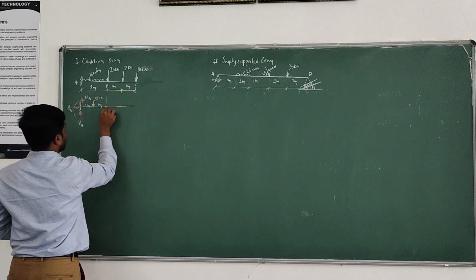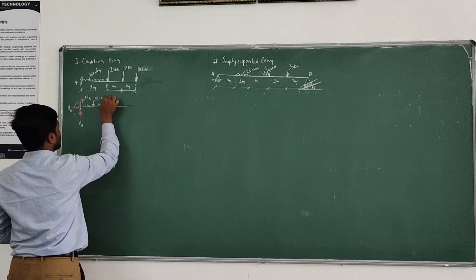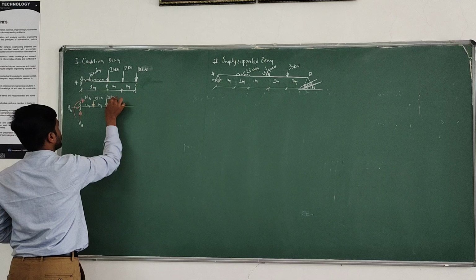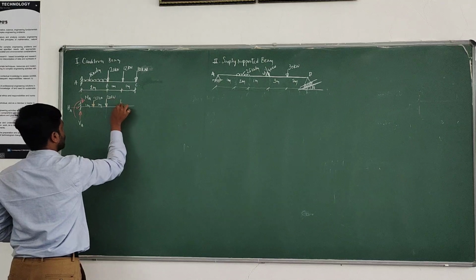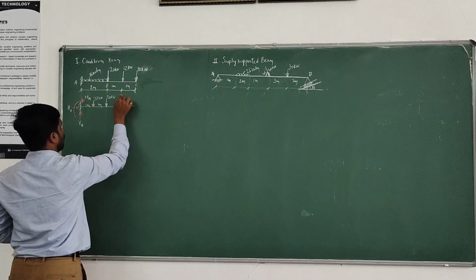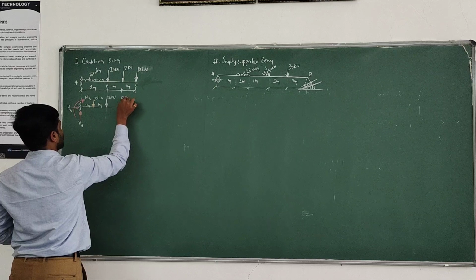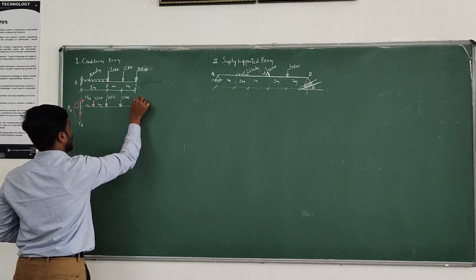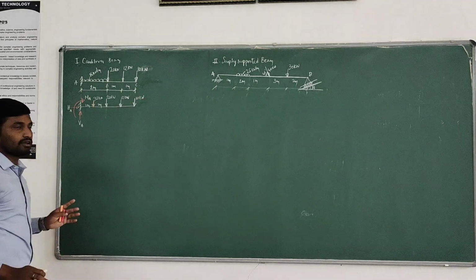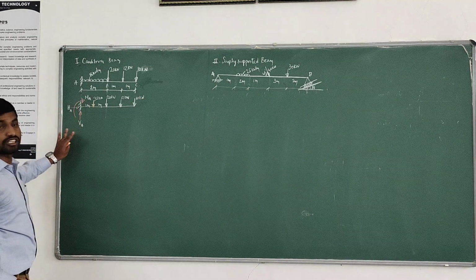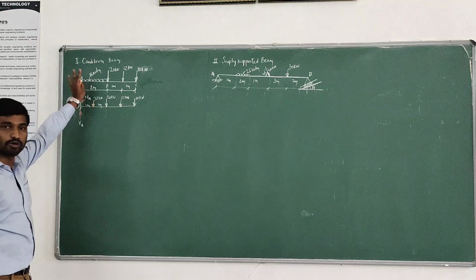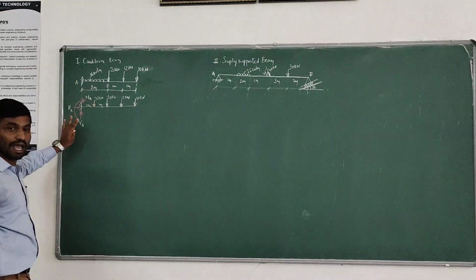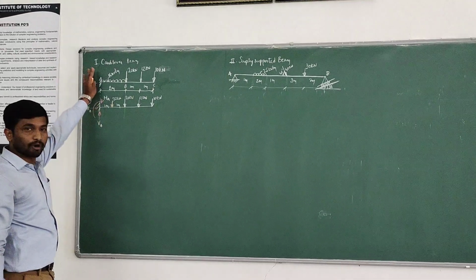At BC, here we are having point loads, keep them as they are, because in the very first step we are reducing all distributed loads into point loads, and we are keeping whatever point loads there are as they are. This is the free body diagram. So here, based on support conditions, I have written the reactions. Here it's a cantilever type of beam.